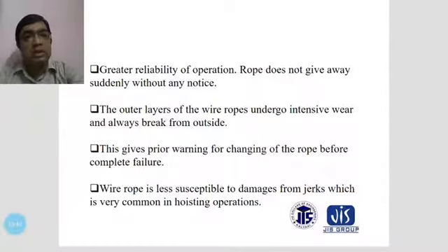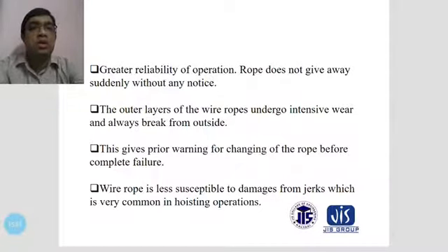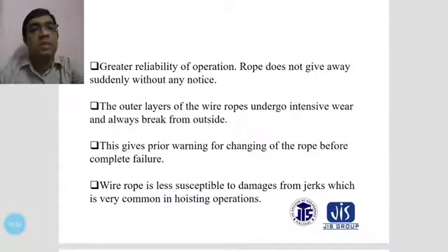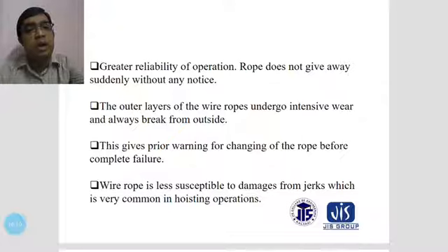Another thing is that wire rope is less susceptible to damage from jerks, which are very common in hoisting operations. Jerking comes when you have to transfer materials over a long distance, or when the road is not very good, so different jerking will be found during the transfer of materials.